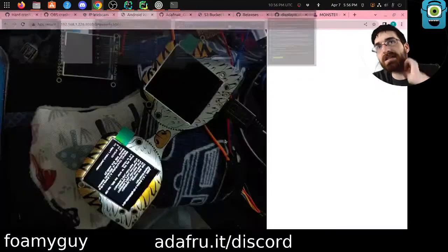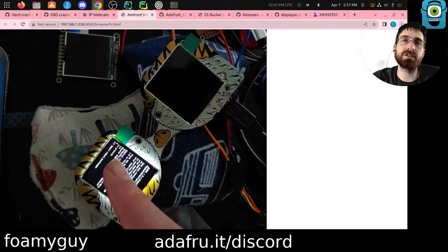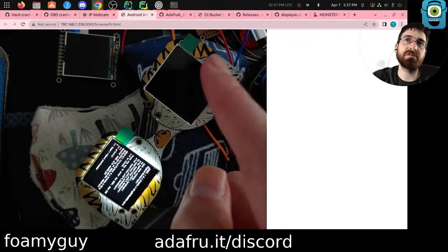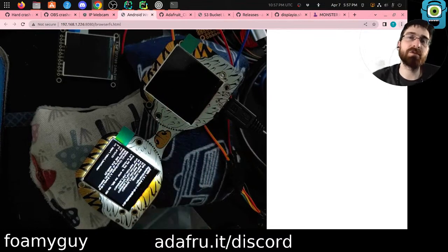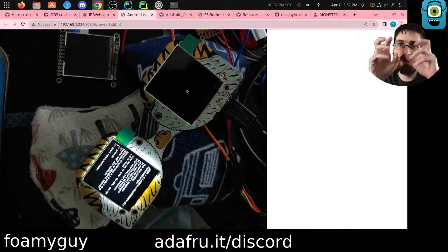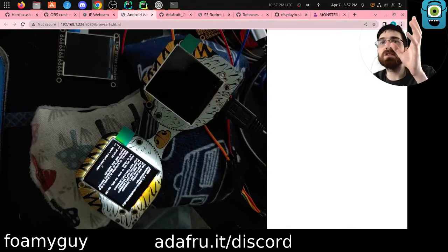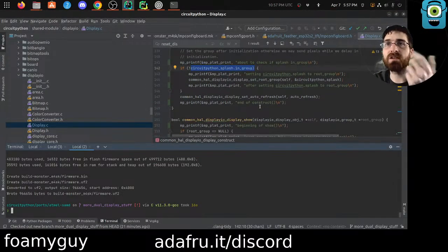I think ideally we would not swap, right? I feel like it would be ideal if at this point when we got here by pressing Control C once, the splash was over here, because that's the built-in display. Realistically, the right display should only ever be used from user code on this device. It should be only if the user code initializes it and only whatever they draw on it. I feel like the splash should always be on this display because that's the built-in one. That's the one that's defined inside the board definition. But I guess it goes to this one because it calls start terminal?